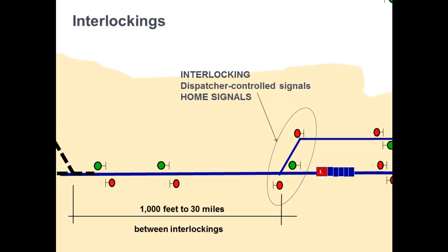They are electrically interlocked for safety. Okay, so in this slide, using the illustration that we have a westbound train, how would you explain how they work in unison? Well, the dispatcher first sets the route. This means that he electronically throws the switch, then he electronically requests that the signal be cleared for a route. The interlocking signal indicates what is detected through the track circuits.